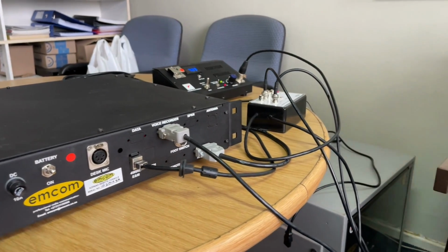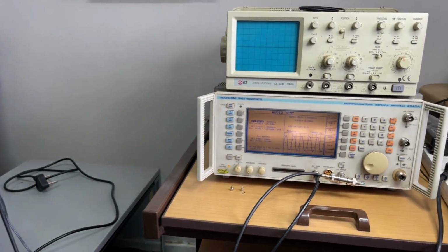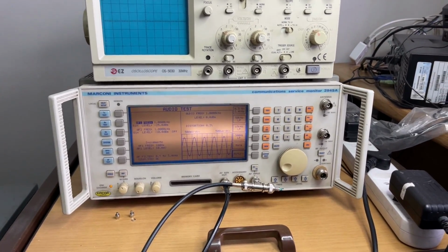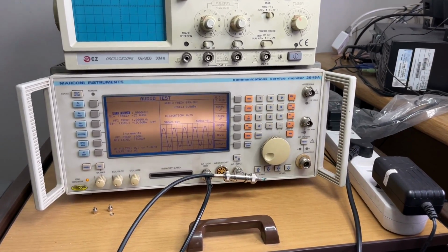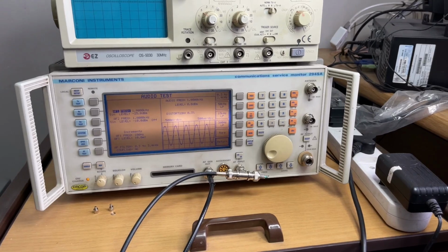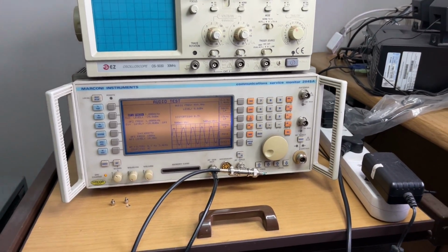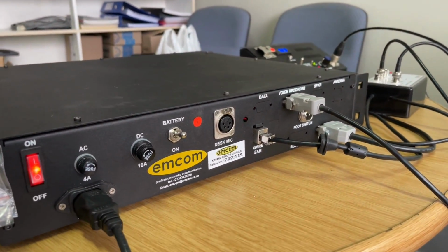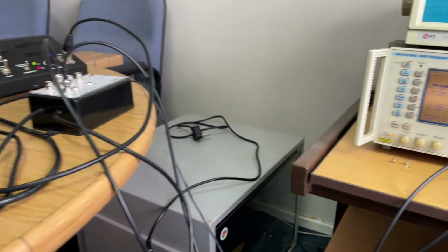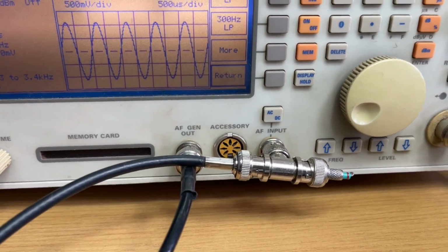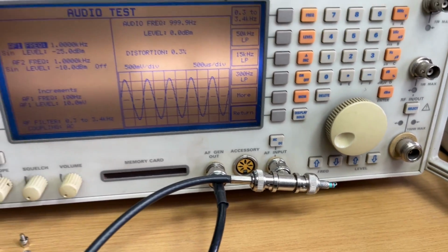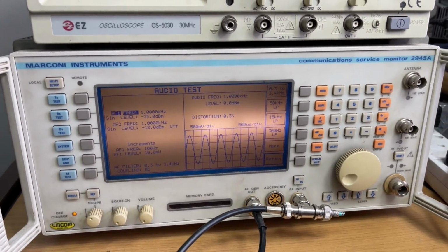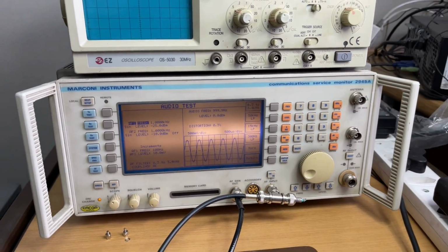Right, so basically the key elements to remember is that when we're testing the E&M incoming, it's at neg 10 dBm, and we remember that we only terminate to 600 ohm on the recorder out during those tests. However, when we're testing the headset microphone, instead of neg 10, we have a neg 25 input, and your 600 ohm termination will remain for the duration of the test on AC input, which of course is your E&M out, as well as your recorder out, which needs to be terminated at 600 ohms. And that concludes the tests.